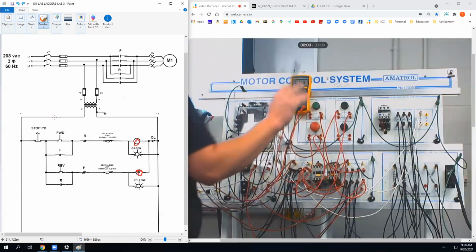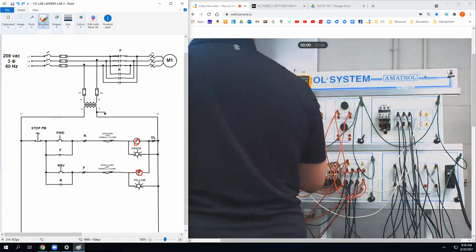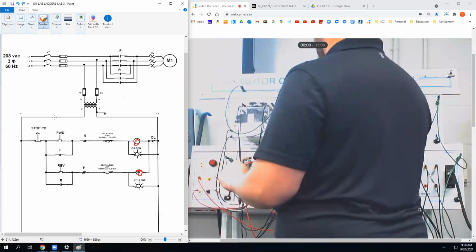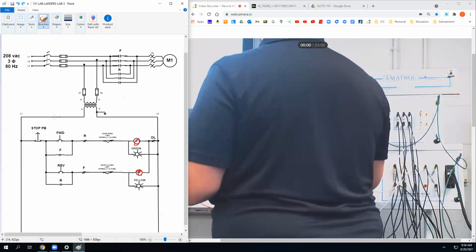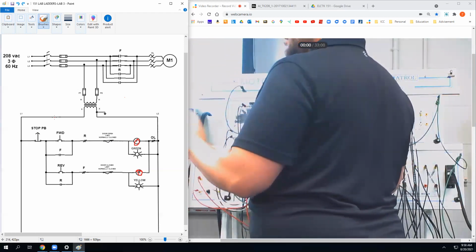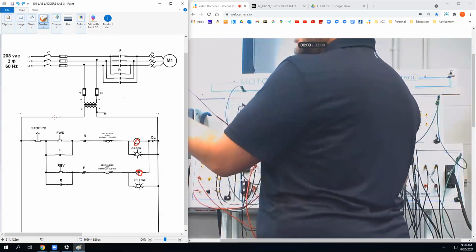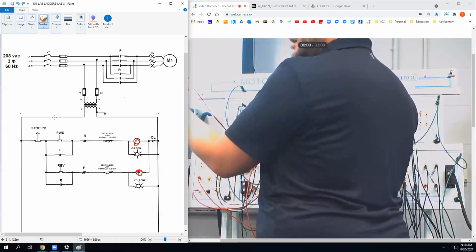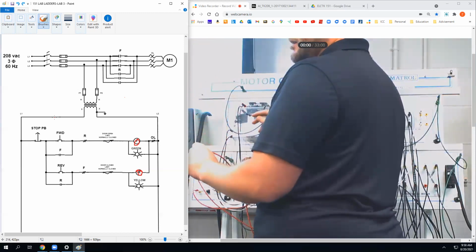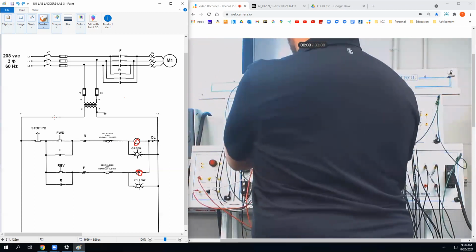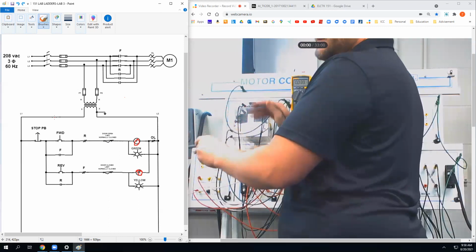By the way, I just want to throw this out there. I should have voltage here, right? Let's say that I did. If I plug one lead of my meter into here and touch that, I'm going to get bit, right? If there's voltage on here, because your meter is just like another wire in the circuit. You're paralleling your meter with this point to see if there's a difference of potential there.